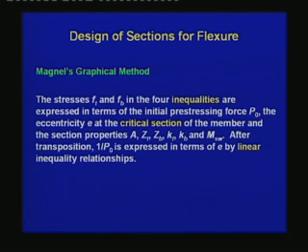After transposition, 1 by P0, that is the inverse of the prestressing force at transfer, is expressed in terms of the eccentricity E by linear inequality relationships.